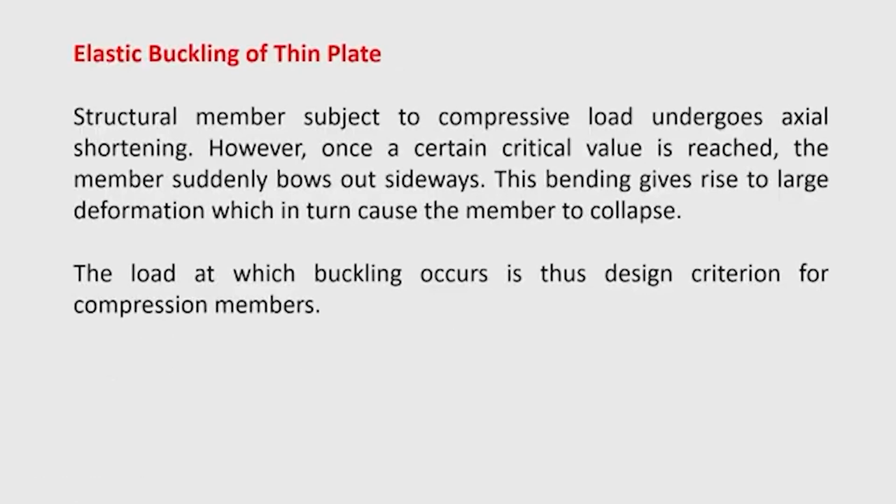Now, let us discuss in brief what buckling is. Any structural member when subjected to compressive load is liable to be buckled when a certain critical value is reached. When the critical value is reached and just exceeded, the member suddenly bows out sideways.